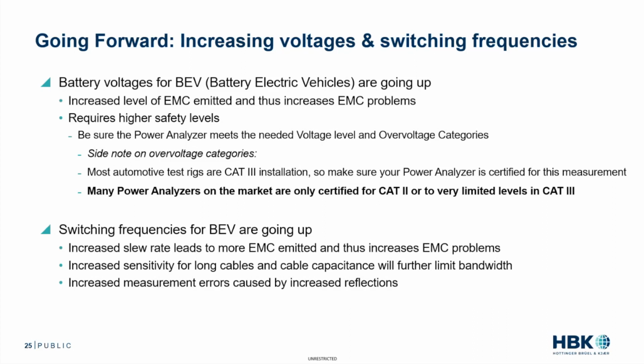So this is going to require higher safety levels, and you want to be sure that the power analyzer that you are using is going to meet the needed voltage level and the over voltage categories. So just a side note on over voltage categories, most of the automotive test rigs are Cat 3 installations. So you want to make sure that your power analyzer is certified for this measurement, especially since safety should be